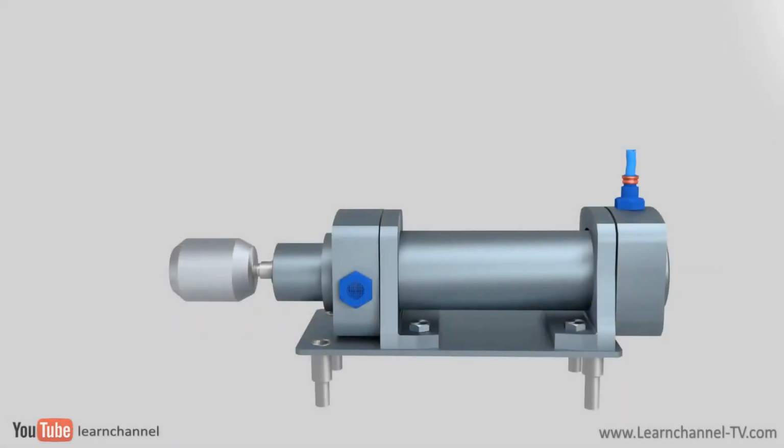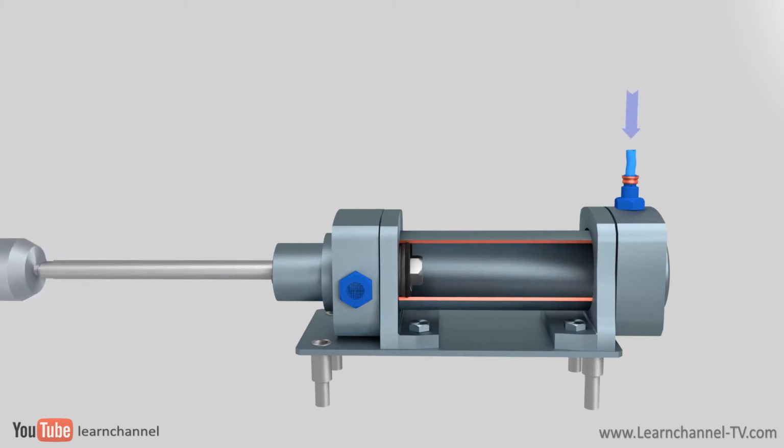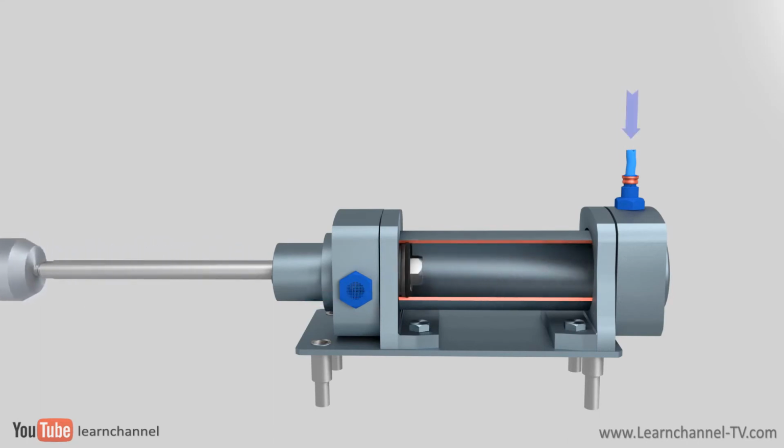In single-acting cylinders, only one chamber is inflated with compressed air. That's why a piston force is built up in only one direction. The inbuilt spring has the only function to retract the piston automatically when no pressurized air is switched to the cylinder.